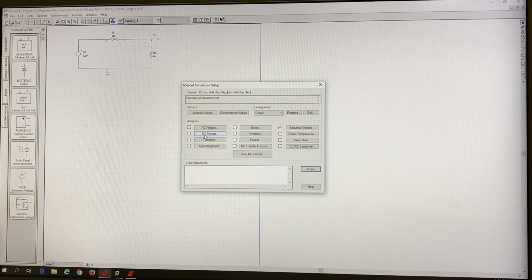So it's dependent on the voltage. The steps are voltage steps. So you're saying at every 0.01 volts, how is my circuit going to behave? That's a DC sweep. You are sweeping, let's say, from 0 to 5 volts, but in increments of 0.01 volts. You want to see the behavior of a circuit in these voltage steps. That's a DC sweep.